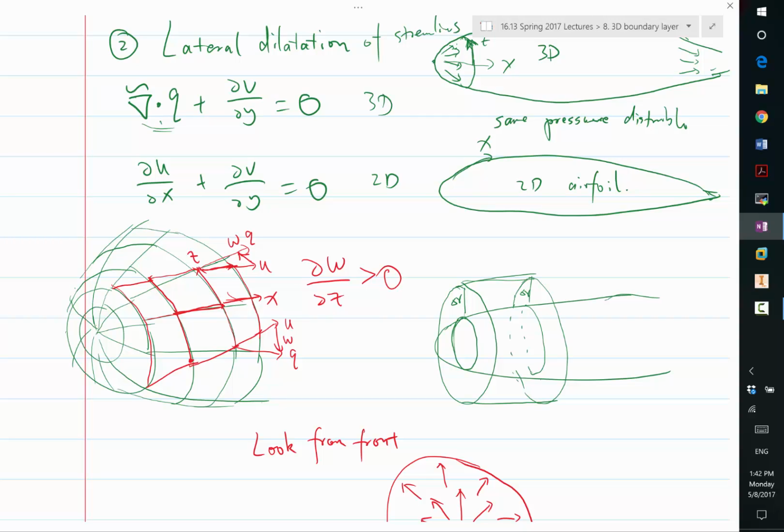So why does du/dx have to stay the same? It doesn't have to be the same, right? I'm just thinking of a hypothetical thought experiment. Or imagine you start solving a time-dependent differential equation, starting from a boundary layer profile that conforms with the two-dimensional airfoil case. How would it evolve? In which direction would the boundary layer evolve?